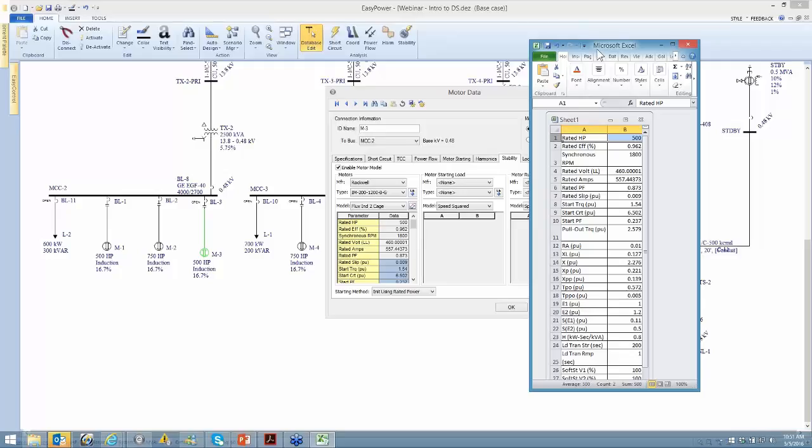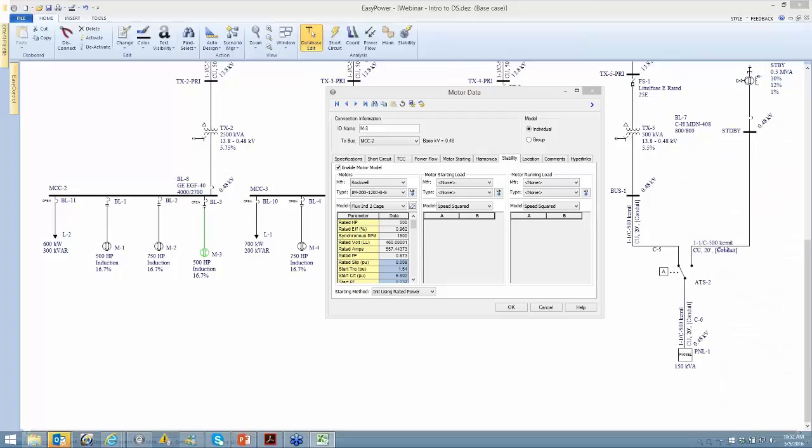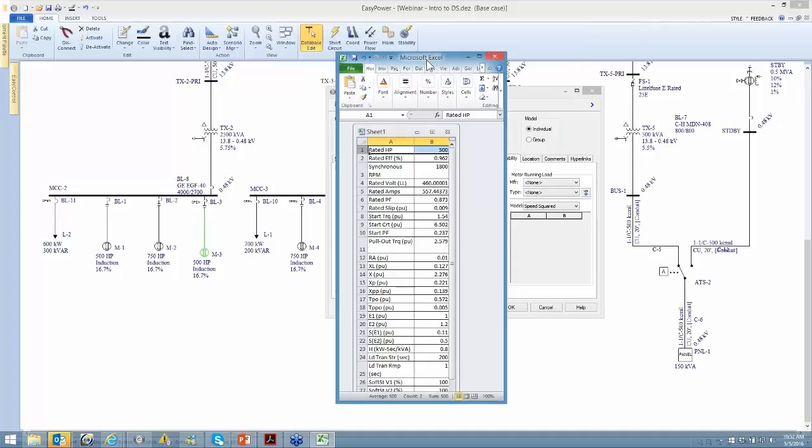And I'm going to ask myself, how can I simulate a condition of the motor starting when I have, let's say, a load that changes, let's say a clutch that changes the torque on the load, provided the feedback from the load to the motor. And so I'm going to effectively simulate that by a change of inertia. In this case, we're going to start at 0.8 and see what happens when I change that after the motor gets partway up to speed. How does that affect the rest of my system?